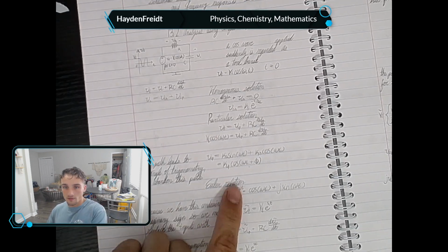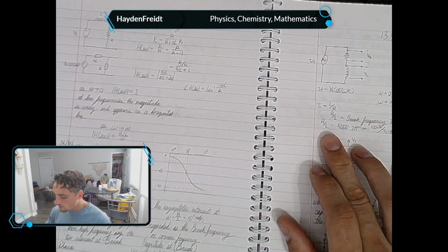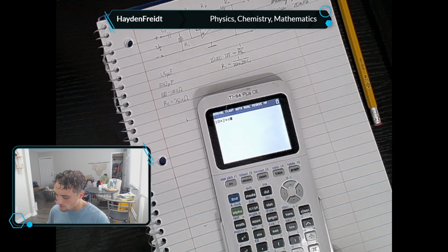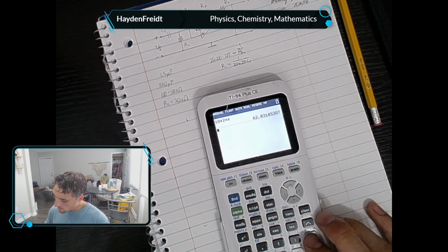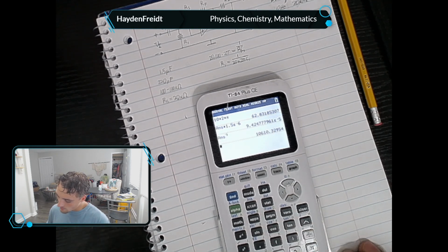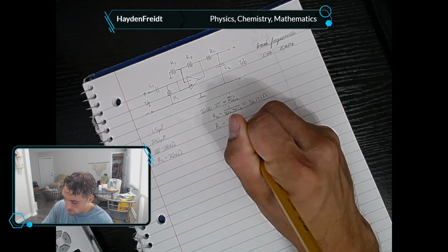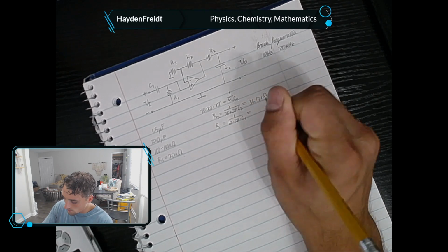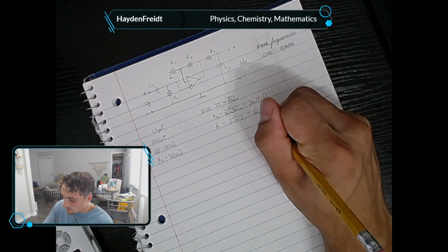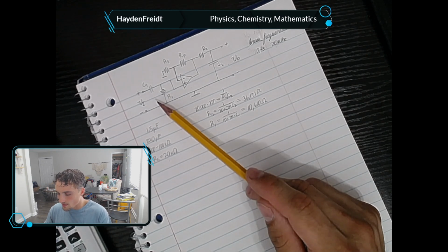That's the Euler relation right here. It's just our alpha. 10 times 2 pi, so now we're working the lower frequency. 10 times 2 pi, E to the negative 6. Inverse of that. Okay, so that's within range. 10 hertz times 2 pi times C1, inverted, equals 10,610 ohms.